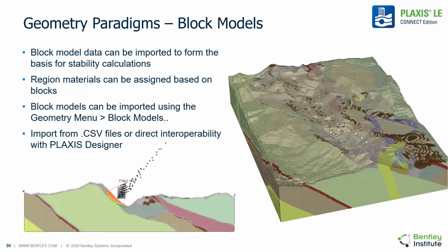The block model data can be imported to form the basis for stability calculation. Each of the blocks will have a lithology assigned, and regional materials can be assigned based on the blocks. These blocks can be imported under the geometry menu, and users can bring them in from CSV files or even PLAXIS Designer.